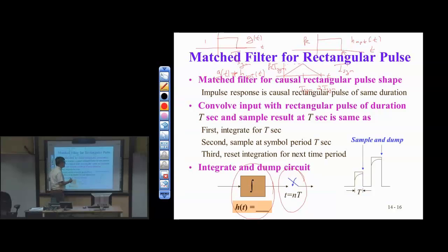That's it. Now the rest of the story in the matched filter is that after the matched filter, I sample at the symbol time. So I'm going to do the matched filter, and then I'm going to sample at the symbol time, right at this peak value, which is great. That means that's where I have the strongest signal power. Excellent. So that's the standard way of doing the matched filter.